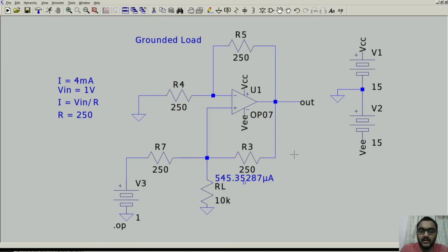So in this experiment, we saw how we can make a V2I converter using an op-amp. We also saw that if we want a low voltage, low current at output, we can use an op-amp. But if we want a highly efficient V2I converter, we cannot make this using a homebrew circuit. For that, we need a current mirror to increase the gain of the system. And then we saw the functional block diagram of the XTR111. The simulation files of this experiment are given below in the link.